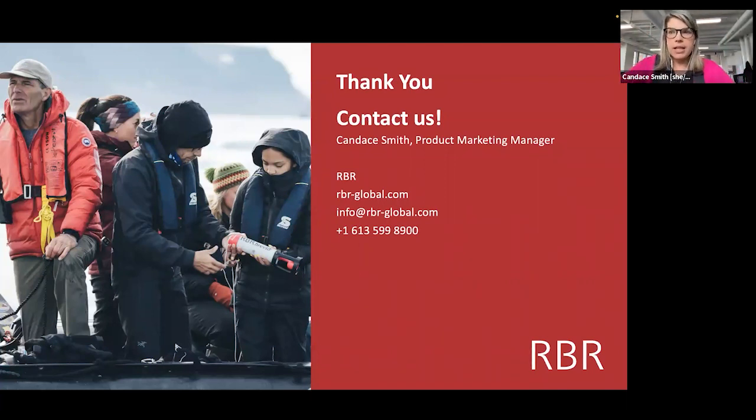And the second thing I would say is get your CTD calibrated every year. When we get your CTD in-house, it's not just sent to the Cal lab and that's it. Our service technicians take it and do a whole process of checks on the instrument to make sure that everything is up to snuff. They check things like the sleep current.